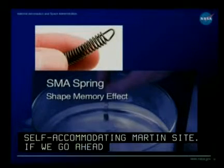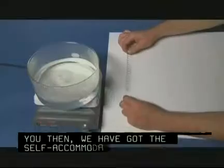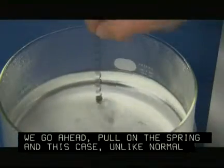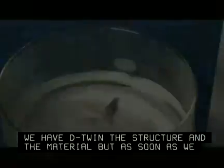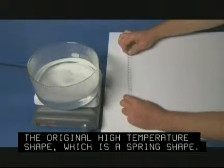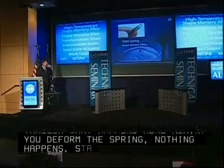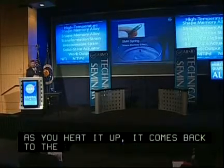We've got the self-accommodated martensite. We go ahead, we pull on the spring. In this case, unlike normal springs, it doesn't come back. We've de-twinned the structure in the material, but as soon as we heat it back up, it comes back to the original high temperature shape, which is the spring shape. So this is just a view of going through what happens here. Again, you deform the spring, nothing happens. It stays in its deformed, de-twinned shape, but as you heat it up, it comes back to the original spring shape, which is your high temperature shape. Can I have the next slide, please?